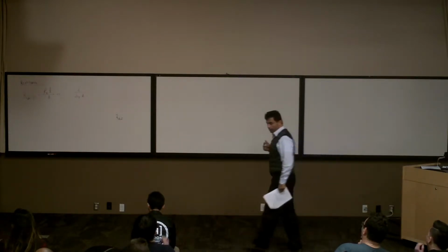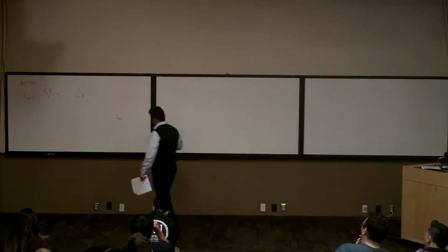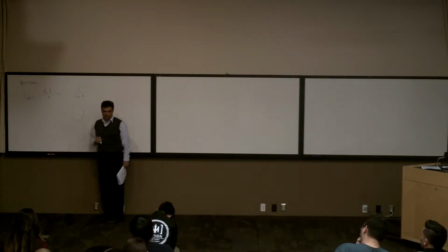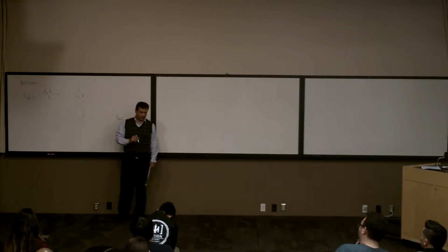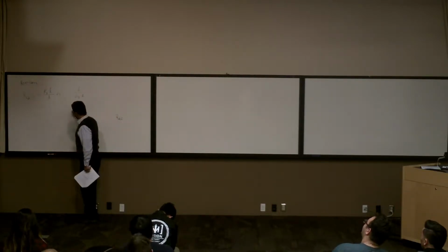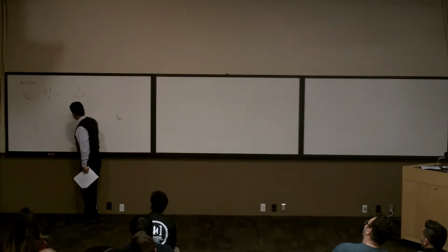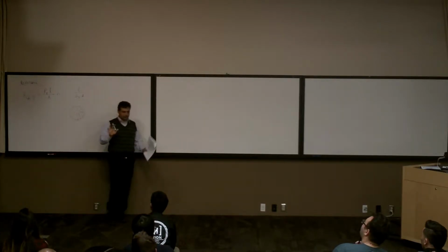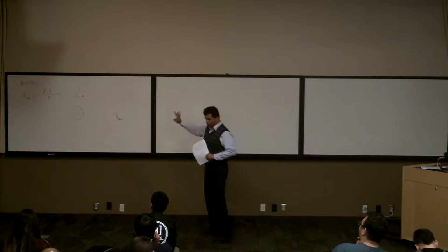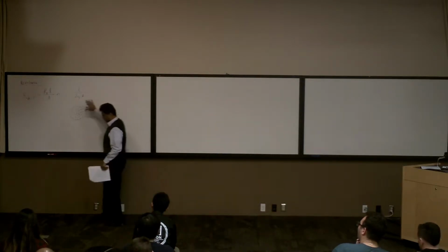I think all of you are familiar with the skin effect, right? If you have a conductor, this is a cross section of the conductor, and we have some current going through it. The current density is pretty uniform everywhere if the current is DC, so basically we are using all the area of this cross section.